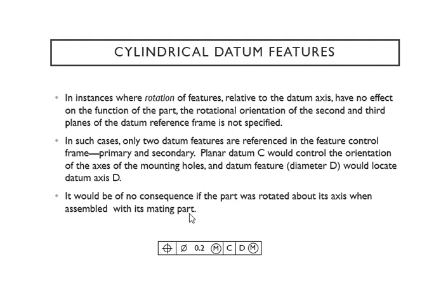And of course you can rotate because the set is so, yeah. You can rotate it, but you're not going to get any kind of bad effect. So that means there won't be any consequence, meaning this control frame will still be controlling that, and your primary and secondary datum features won't get affected by rotation.